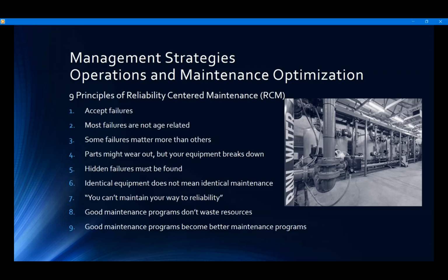And third, extend task intervals. Do this based on data analysis, operator and maintenance experience, or simply on good engineering judgment. Remember to observe the results. The shorter the current interval, the greater the impact when extending that interval. For example, adjusting a daily task to weekly reduces the required PM workload for that task by more than 80%. Often this is the simplest and most effective improvement you can make, and is some of the improvements we've made across many of our maintenance programs.